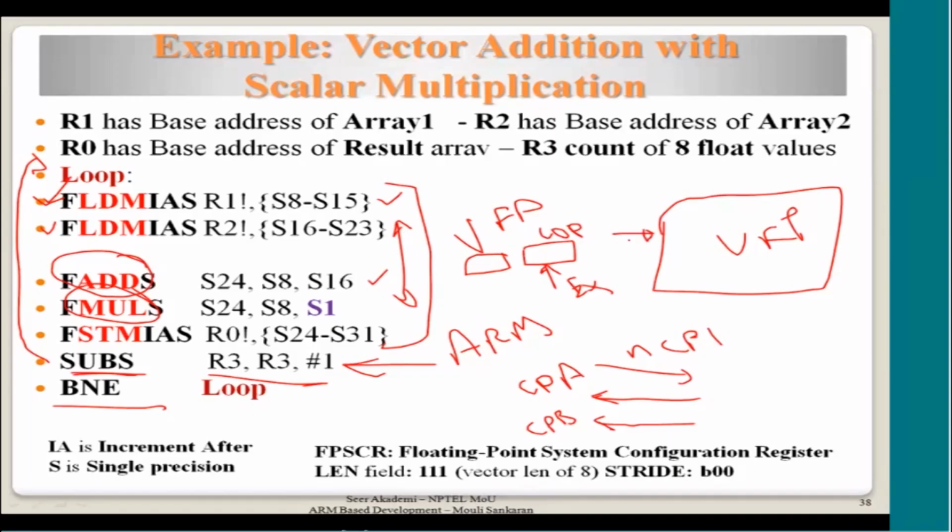Okay, so there is no need to have any other mechanism of waiting. The waiting is implicit, because that is a condition that the ARM processor has put in: unless the instruction is accepted by the floating point processor, do not go ahead with the execution. So the ARM processor will get blocked, because this instruction will be executed faster. This also may be done faster, because ARM is doing a small integer arithmetic, whereas these are all floating point jobs. So it will get blocked when multiple iterations of this have to be executed.